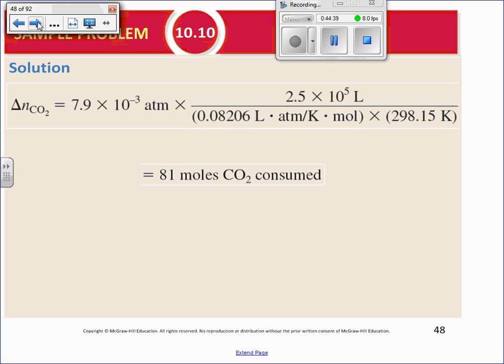So why would that be important to know? Well, there's so much oxygen and you're building up CO2, but you only have so much lithium hydroxide for it. So after a while, you say, well, if I used this much CO2, I've used up this much lithium hydroxide. And if you get to the point where you run out of lithium hydroxide, you can't use up the CO2 that's going to build up in the submarine. And so you've got to surface and replenish that.